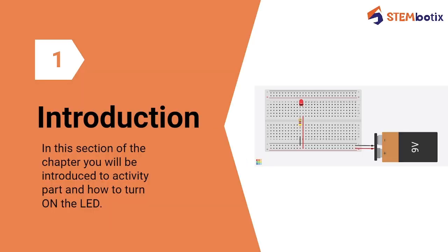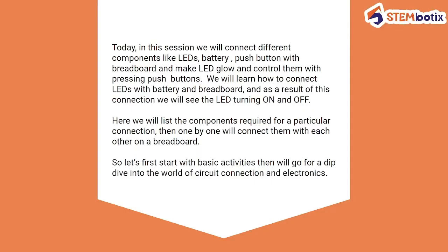So let's start our first section, which is the introduction section. Today in this session, we will connect different components like LEDs, batteries, and push buttons on a breadboard, and we will also see how you can connect all these components online on software called Tinkercad. You will see how to make all the circuits in Tinkercad and make an LED glow.